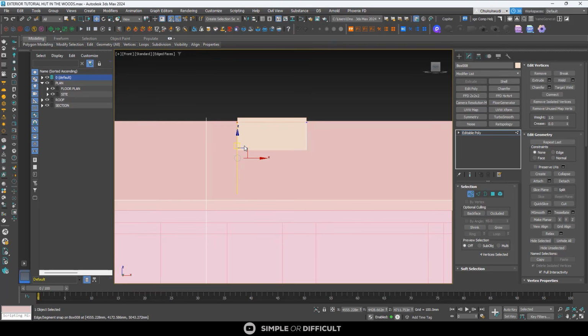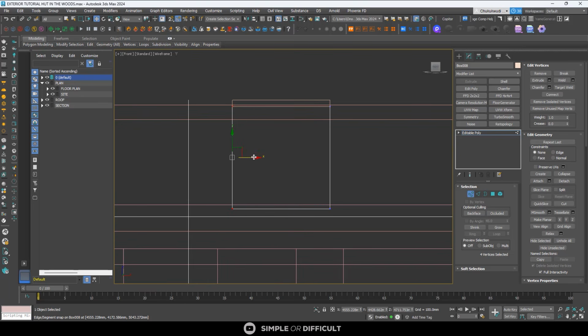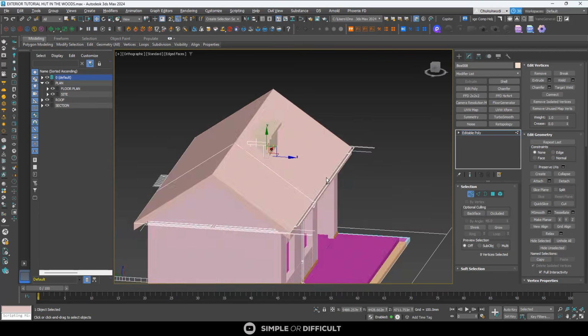But if you need to get an actual measurement, you already know how to do it. If you want to make this thing exactly the same size, left and right, you can just scale it like this. Use the scale tool, right? Scale it only on X. Make sure that when you are only on the X axis, you can see the line leading to the X axis is highlighted. So we'll use it, drag it this way. It will come in, and they're the same size, back and forth.